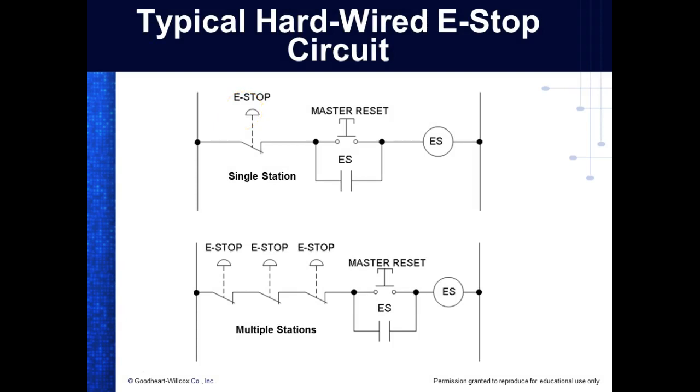Well, I got this off the internet somewhere. These are typical hardwired e-stop circuits. This would have an e-stop. This is a non-detent e-stop. So this is the symbol, by the way. This is the international symbol for a normally closed contact. This is normally open. So it's basically a standard run-stop circuit, right? Understand?